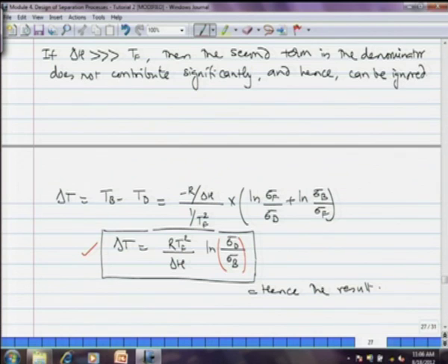What we need to know to get delta T is just the temperature of the feed, the average latent heat of all components, the distillate composition and the bottom composition, and relative volatilities. With this simple data, you can get a very crucial parameter, the temperature drop across a distillation column.